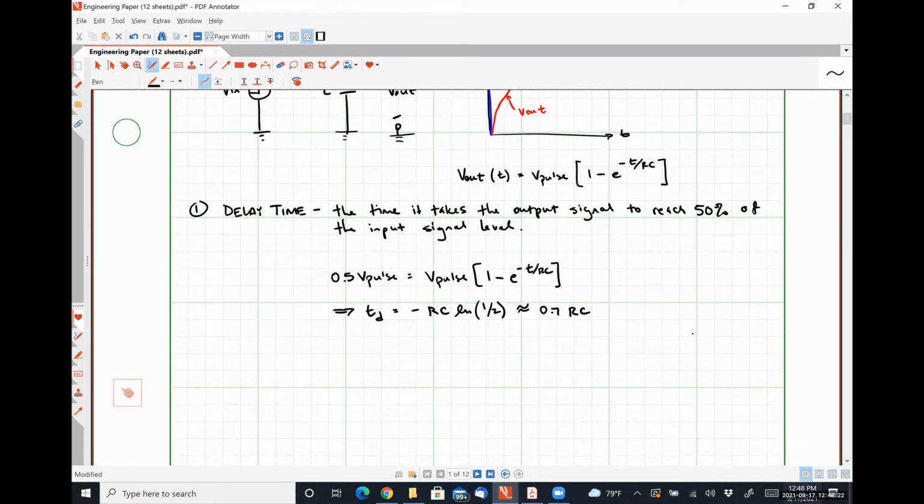We are also going to define the rise time. And for those of you in the lab, and I mean the ELEN 439 lab, the rise time definition that we're using here is the exact same rise time definition that is used to determine the slew rate of an op amp. So if any of you guys are researching that, this should look familiar.